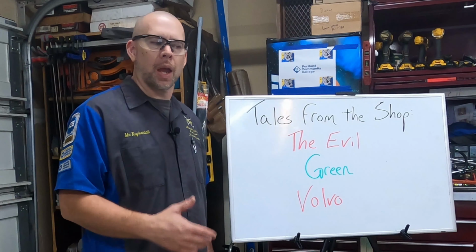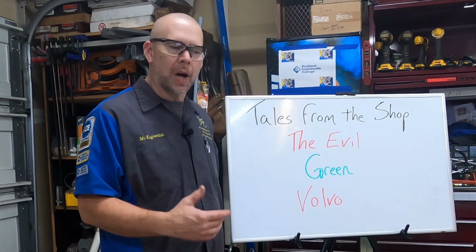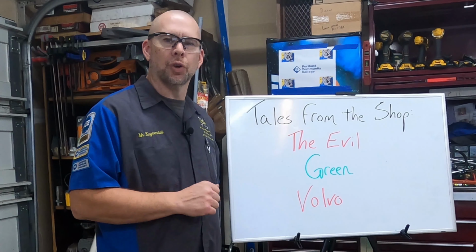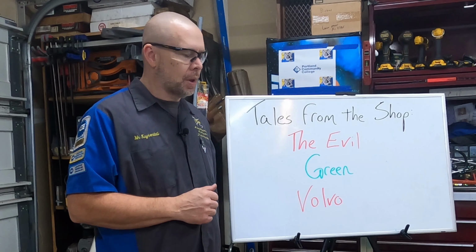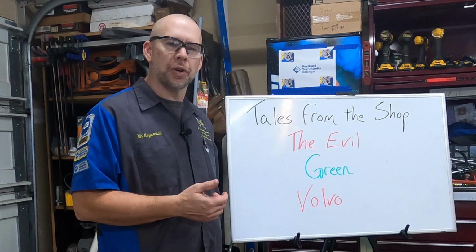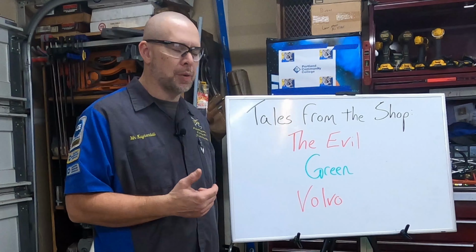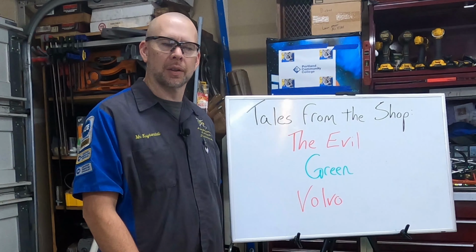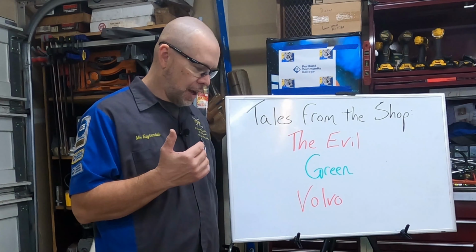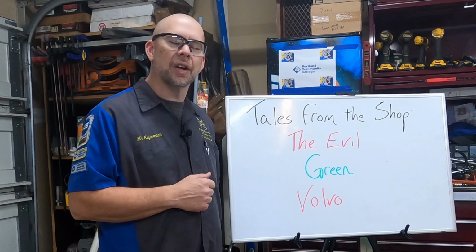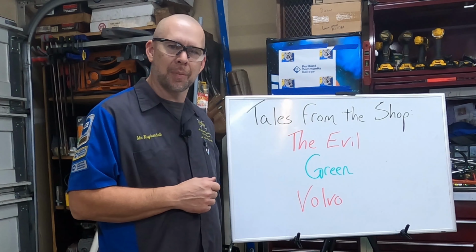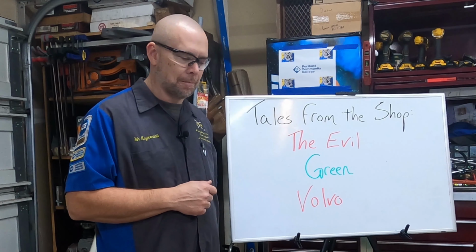All right. I take my lab scope, I connect it up, I get a fuel pump reading. I figure out my fuel pump RPM. It's spinning somewhere between 3,500 and 4,000 RPM when it should be well over 6,000 RPM on this car. I have a situation where my current draw is very high, 12 to 14 amps, much higher than it should be on this car.